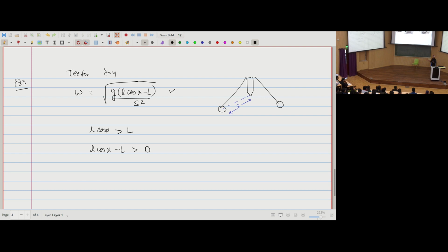Now if you want it to be more comfortable for the people inside, if somebody who's designing the ship purely cares about the comfort, and has no idea about stability, they will end up designing it such that the oscillation frequency is very small. But then what happens is, the ship may topple. Okay? So there is a trade-off between frequency and stability. Larger frequencies are highly stable and smaller frequencies are close to the threshold of stability.